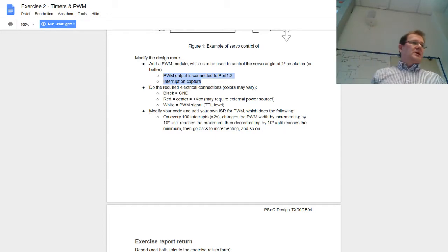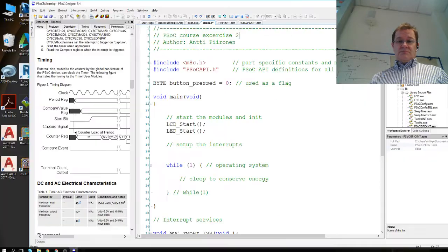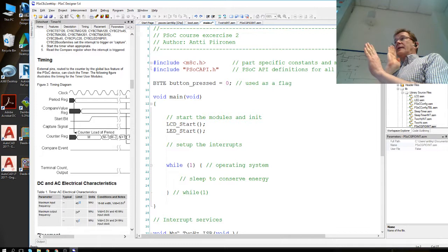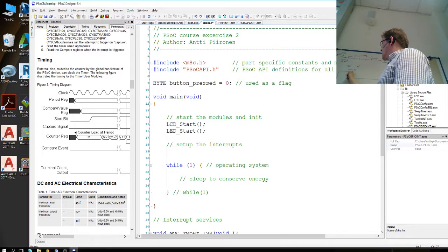Good. So, okay, how to do that? I will give you more hints, but not all the hints anymore, since you already know how to make a hook on the PWM interrupt service routine. You also need to calculate how to get a 20 millisecond period. And how much resolution do you need on your PWM module count?